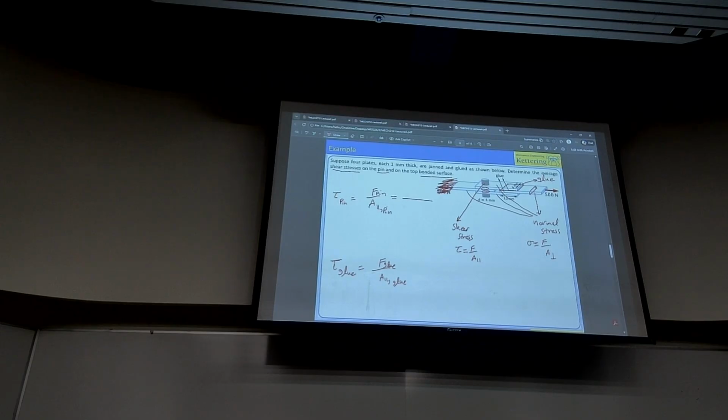I'm saying that this pin could fail in two ways. One way is that the force that comes from the left plate causes the failure on the two surfaces. The second criterion is this. I could say that either the top or bottom section is failing by the respective force from either the top or the bottom plate on the right. Does that make sense? It turns out both are equal.